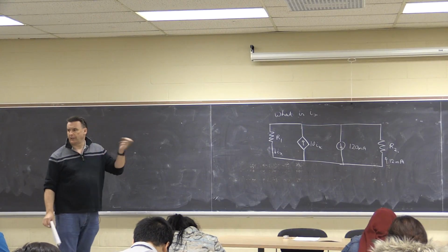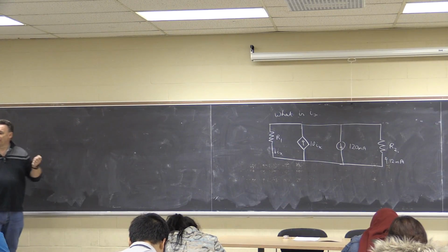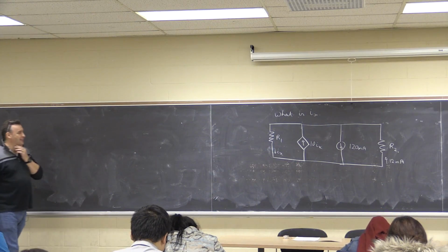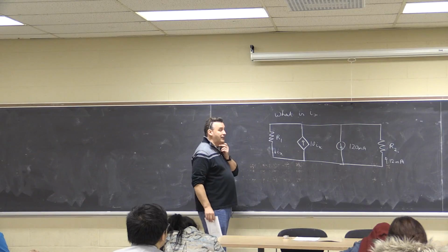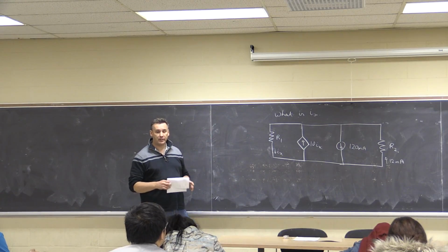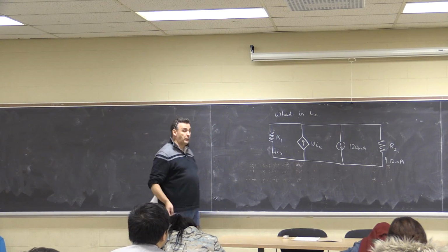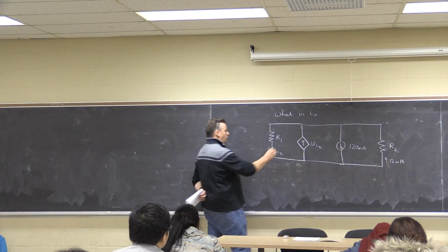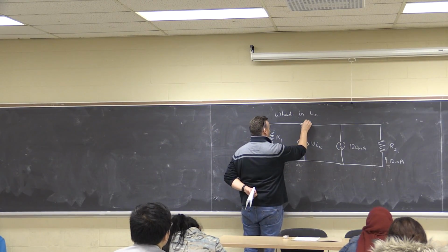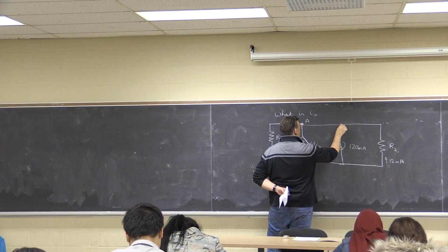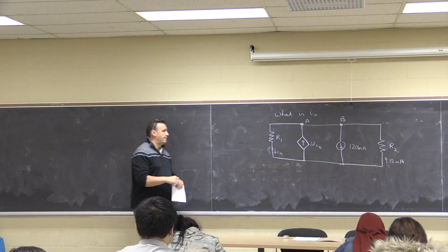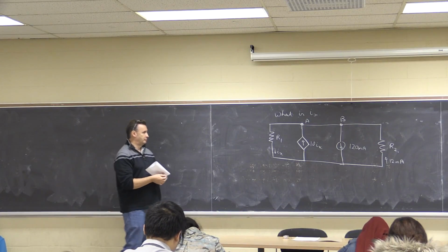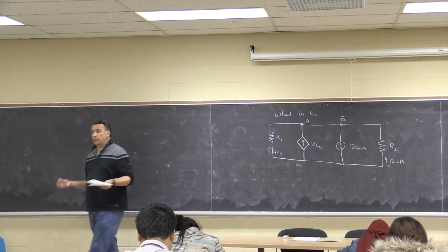You'll learn a little bit if I write down the answer. You'll learn much more if you try and figure out what the equation would be. So take a couple of minutes and see if you can write out what equation or equations we'd need for this circuit. If you want a hint, let's say there's a node here, A, and another node at B. Kirchhoff's current laws apply at both nodes.